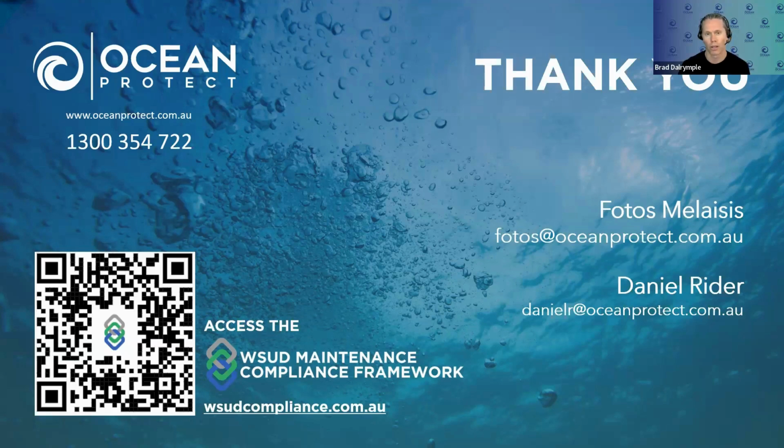So just to clarify, if you don't enter the pit, if you're literally standing on the ground level and say sucking it out with a sucker truck, for example, do you still need a confined space entry ticket for that situation? And it equally could apply to, say, a wet sump GPT. If you're standing near a wet sump GPT, not entering the pit, visual inspection or a vacuum suck, for example, do you still need a confined space entry? Not necessarily, no. But I think the confined space entry work that we do, in my experience, is also associated with a working at heights permit.